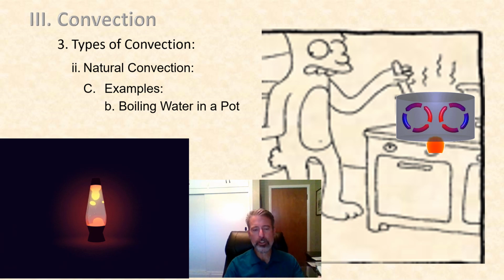So with the gel-like blob, you can nicely see what's going on in terms of convection. You see the decrease in density, the increase in buoyancy, but as the fluid rises up, it becomes more dense and less buoyant, and so it sinks again, falls down to the bottom, gets heated up, and this process repeats. So, like I said, this rising and subsequent falling of the fluid is what we refer to as a convection current.